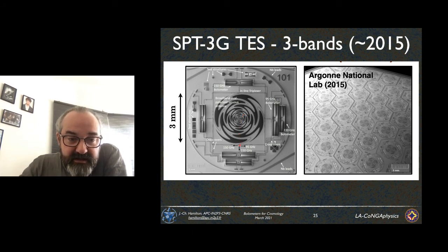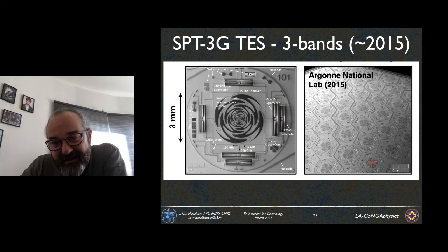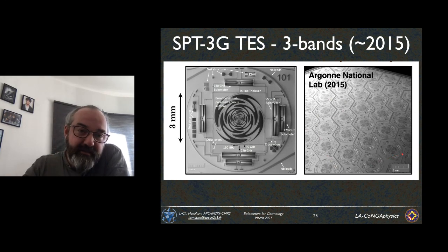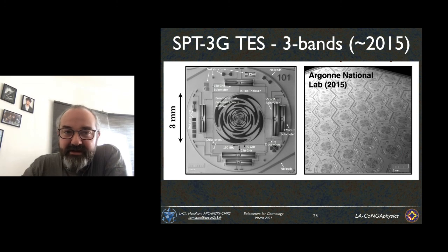Then the signals, in both polarizations, sorry, are split here into 3 parts using filters, so that at the end you have 3 bolometers on the same antenna, 95, 150, and 220. And you have an array of these, and you see that you can detect in 3 bands altogether. So this is absolutely impressive. Very, very nice design for the South Pole Telescope, 3rd generation.